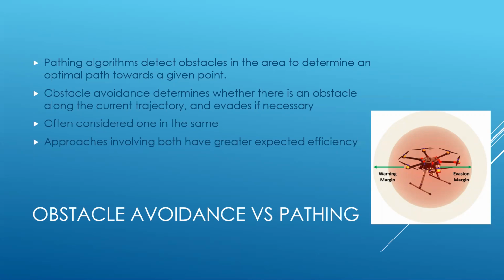At this point, the algorithm may select the path that best brings it towards the target without collisions. In each iteration of the obstacle avoidance algorithm, data must be obtained and an efficient check is performed to see whether any points intersect the drone's current trajectory. It is clear that the obstacle avoidance algorithm is much more efficient than the pathing algorithm, though it cannot accomplish the same results. Suppose that an iteration of the obstacle avoidance algorithm takes only 15% of the time of the pathing algorithm.